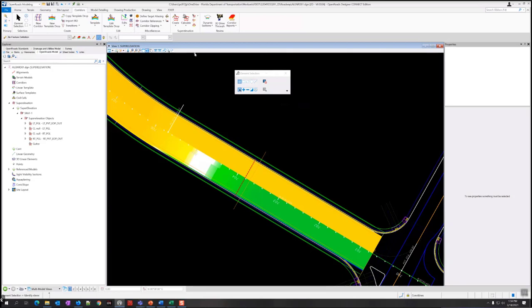We go over here to this button, the little paperclip icon beside the super elevation cross section. Or it looks like the Windows icon, honestly, but anyway, paperclip and Windows icon: Super Elevation Report. Click that, and it asks you to locate the first super elevation section. So I'm going to click this green box around the super elevation, and then reset to complete.